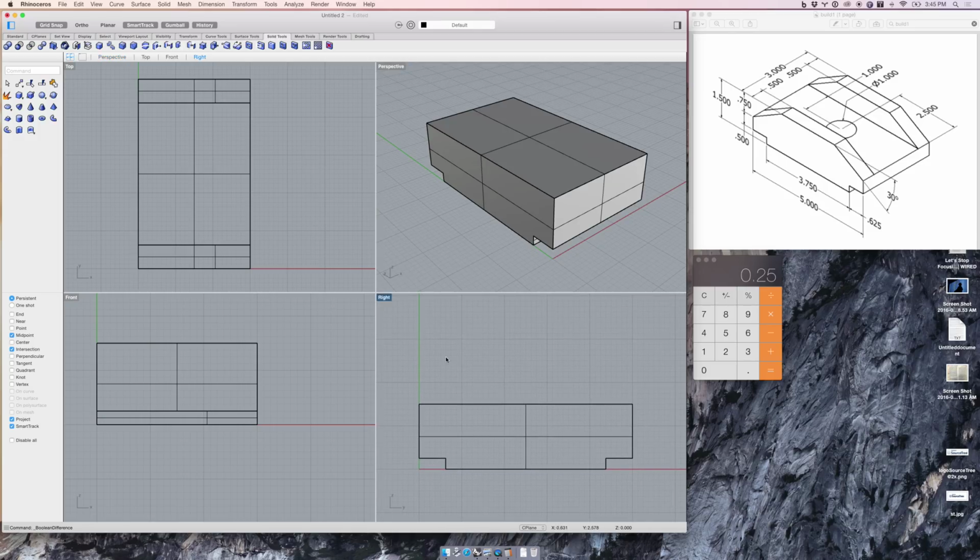So in the right view here, I'm going to draw a big rectangle. Way bigger than I need. About like that. That'll work. And then I'm going to click on it, and you're going to see this thing right here, this green line, red line, and so on. If you turn gumball off up here, it disappears. But I'm going to leave gumball on because it allows me to do something really cool. Check this out. So you're going to rotate. Or if you click on it and then click on that particular rotator, which is I'm rotating around the z-axis, and I say I want to rotate 30 degrees, it's going to shift that thing up.